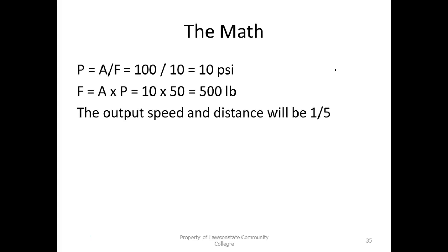We do have a force multiplier, but we don't have a power multiplier, and people think we have these things called power amps, but you've got to understand, we have this other thing called a power supply. So power amps don't create power. If you got a power amp in your car, they don't create power. They manage power. The power's already there.